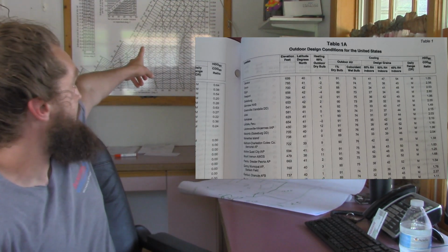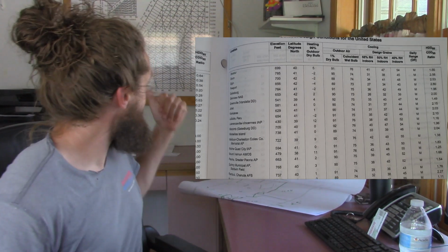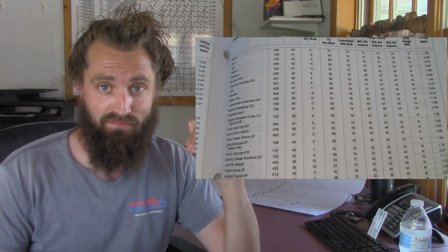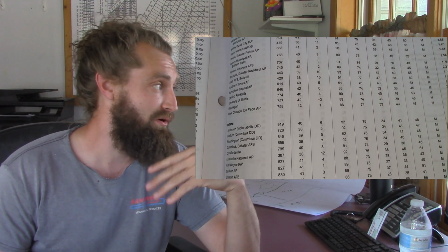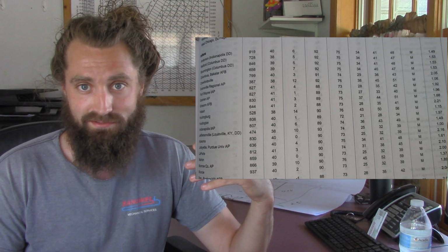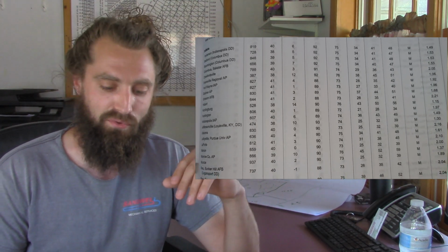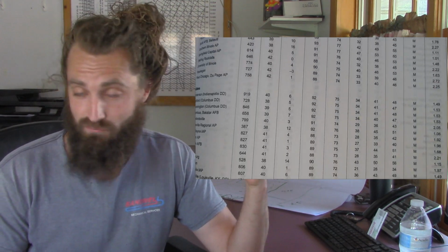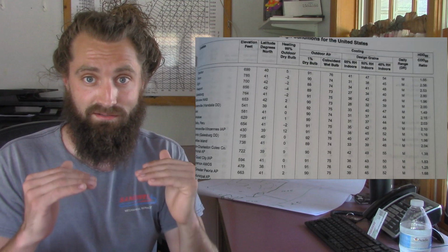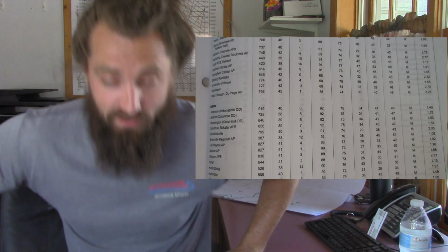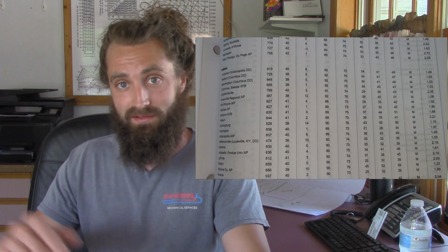For like this psychrometric chart that we've got back here, that is all based on sea level. You get above sea level you have to account for that, okay? Now, if you are a couple hundred feet above sea level, to account for that is a drop in the bucket. But when you get a few thousand feet above sea level, the air is going to definitely react much differently than it would down at sea level. So if you're in Colorado, up on top of the mountain there, we're going to be designing our systems way differently than we are if we're in Miami.